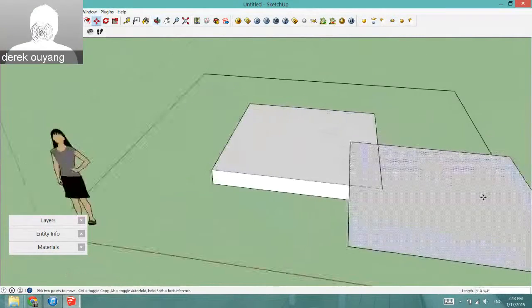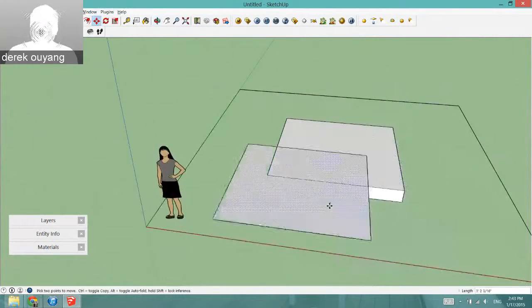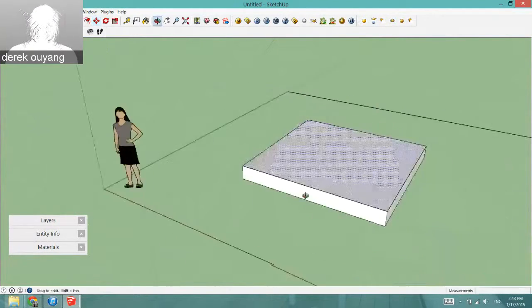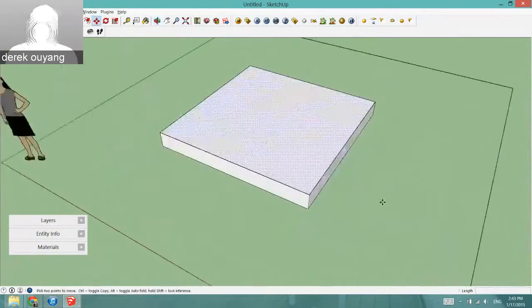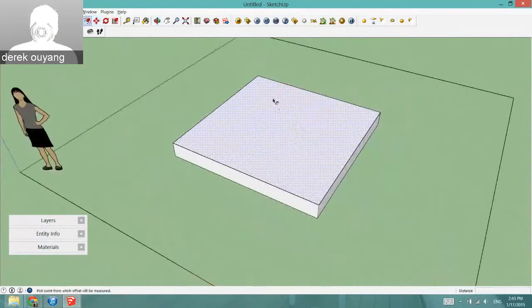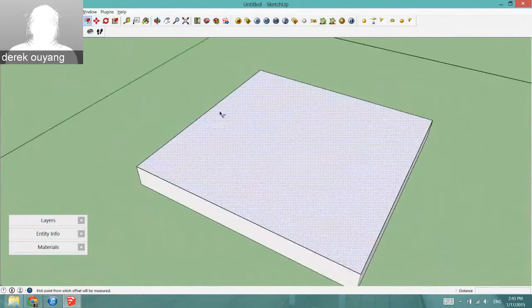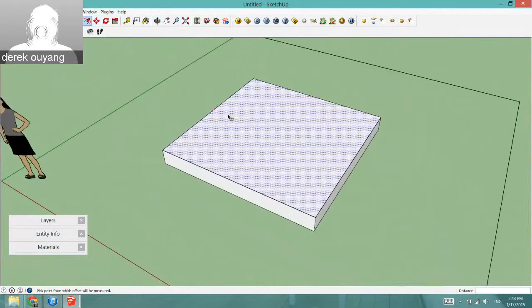There are, in fact, individual lines on top of here and then the surface. They're all independent of the slab you'd created, and they don't stick because you have made the floor slab a group. From here, we're going to switch to the offset command, and then we're going to select the surface, and then we're going to head inwards and type in 1 foot. We're going to have 1 foot thick walls. Click enter. Now you've made 2 separate surfaces.